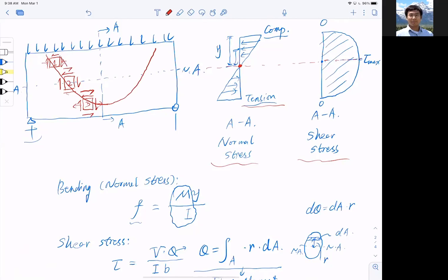So I can keep drawing it, to finish this trajectory of principal tensile stress. As you get lower, the bottom portion gets flatter, and the opening gets wider. These red lines are diagonal tension lines. You can think of them as the primary tensile direction, so the concrete is being stretched along these lines.